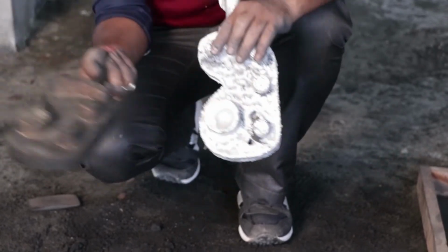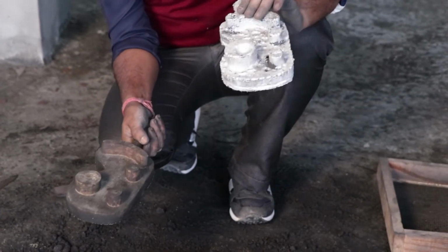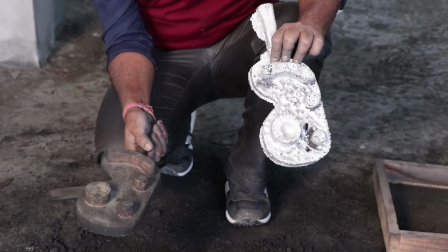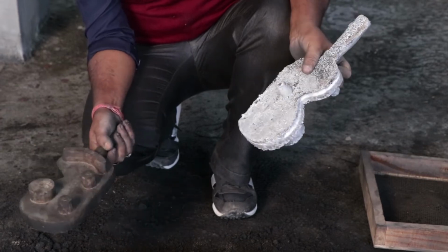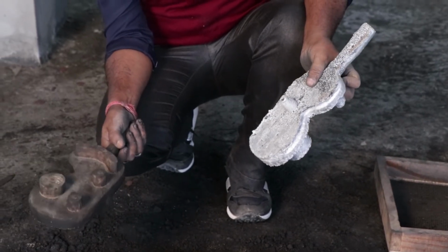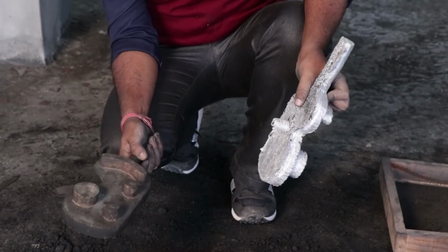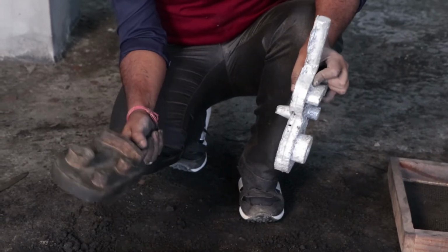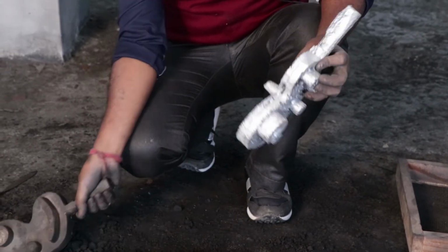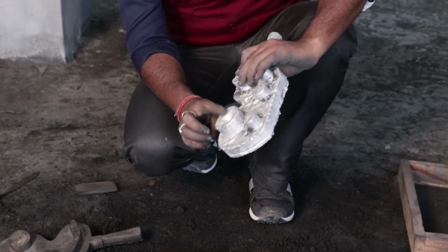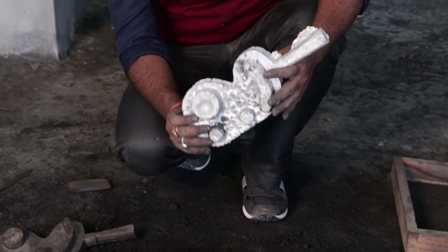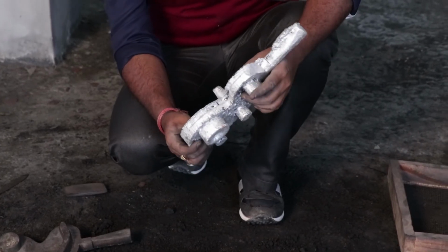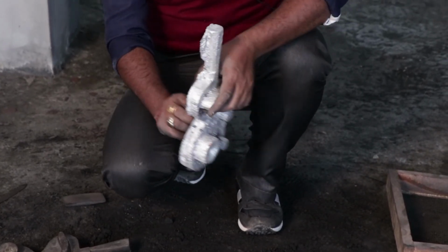As you can see, this is the wood pattern, and finally we got an aluminum pattern over here, which has totally come up. And as sir has already explained, there is a machining allowance regarding this foundry process. So you can see that there are some burrs and some ups and downs over here. This will go to machining and it will become a total gear after completing the entire machining process.